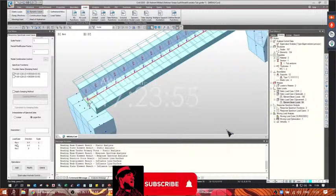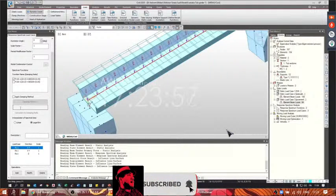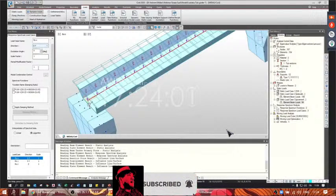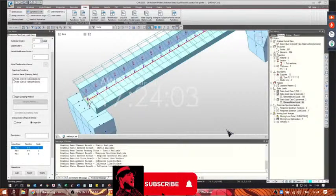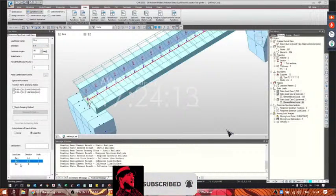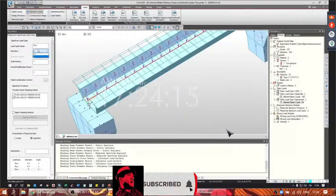We have RSX with an X direction here, and the horizontal spectrum associated. RSY is the same as the first one, but you have an excitation angle of 90 degrees because it's a perpendicular direction, and the vertical component RSZ that has Z direction.